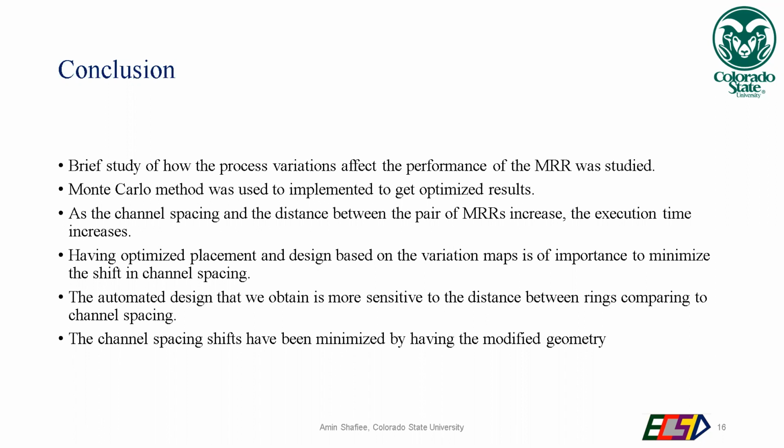Also, having an optimized placement and design based on the variation maps is important to reduce the shift in the channel spacing. Based on the observations, we can conclude that the automated design is more sensitive to the distance between the rings when compared to the channel spacing. And by taking into consideration the modified geometry, the channel spacing shifts can be minimized.